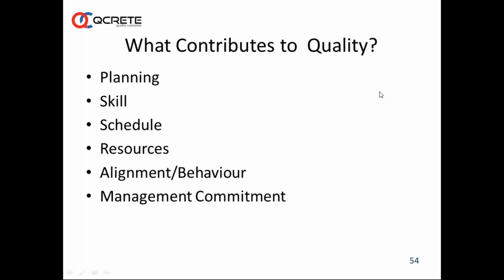But you need to get approval from your customer or client, and you should have a lot of data on this actually. We don't have at this moment commercial experience in these kinds of things. From the 1960s, people have done a lot of trials using a high amount of GGBS in Russia. But commercial applications in India are limited actually. At lab level, people have worked actually. So in short, at this point of time, we cannot use more quantity of GGBS than specified by IS standards for commercial applications.